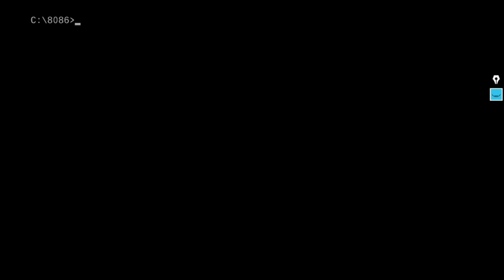For that reason, you have to convert the executable file into the binary file. Now observe this. You have used the command afdebug. Now I'm going to convert this executable file into a binary file using the command exe2bin, space, smclk.exe, which is the executable file. What name should I give the binary file? That's my wish. I'm going to give the same name, smclk.bin. Just press enter. That's it. It's going to create a binary file in the backend.